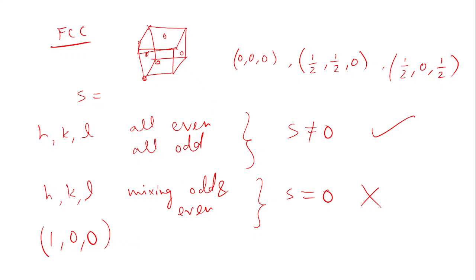Okay, because the 100 plane is there, of course. If it's a cubic, this is the 100 plane, right? The 100 plane is there, but we will not be able to see diffracted peaks from it, if the atom position is on the face.